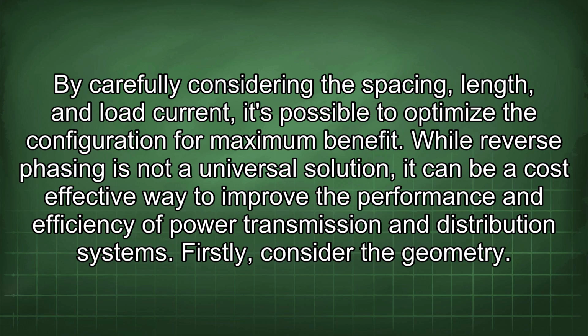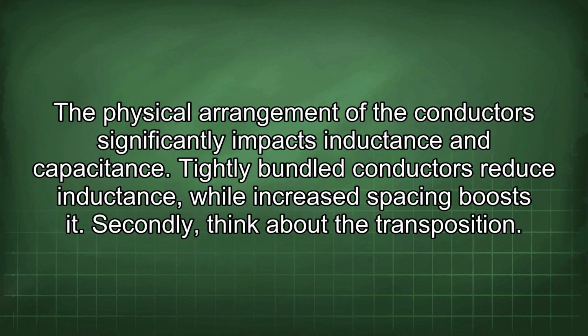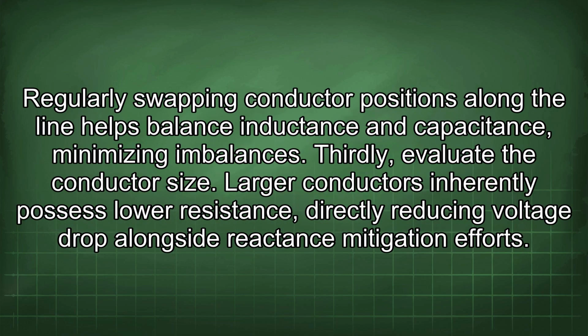Firstly, consider the geometry. The physical arrangement of the conductors significantly impacts inductance and capacitance. Tightly bundled conductors reduce inductance, while increased spacing boosts it. Secondly, think about the transposition. Regularly swapping conductor positions along the line helps balance inductance and capacitance, minimizing imbalances.